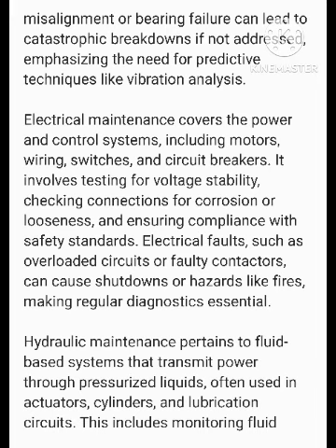techniques like vibration analysis. Electrical maintenance covers the power and control systems, including motors, wiring, switches, and circuit breakers. It involves testing for voltage stability, checking connections for corrosion or looseness, and ensuring compliance with safety standards. Electrical faults, such as overloaded circuits or faulty contactors, can cause shutdowns or hazards like fires, making regular diagnostics essential.